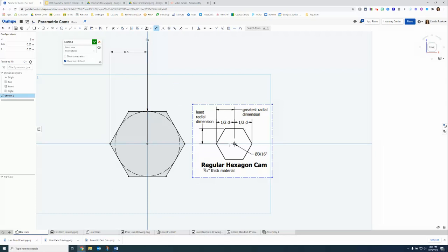Now we need to add in our axle hole. So I'm going to click C for circle, and then go to the origin, click to place, D for dimension, and we are going to use our hole variable. So #hole, click enter, and there we go. I've got my dimensions here, but remember I forgot that we're going to go back to hole and set it equal to what the plans say. So 3/16 inch, and you can see that popped that back down.